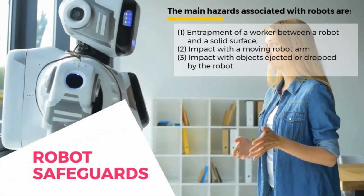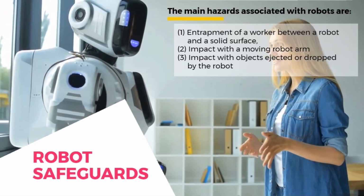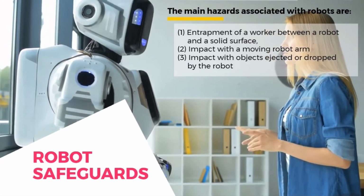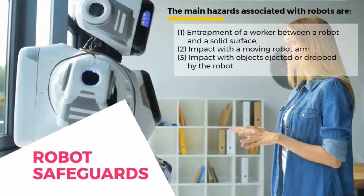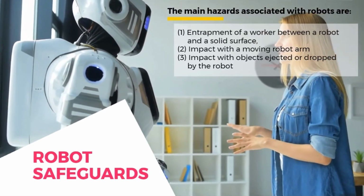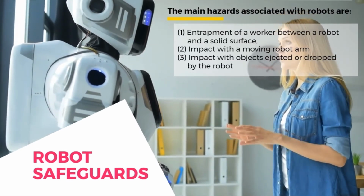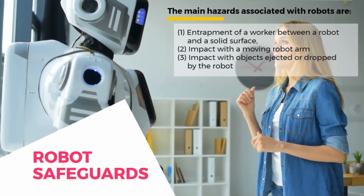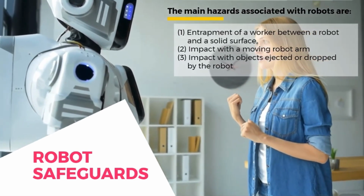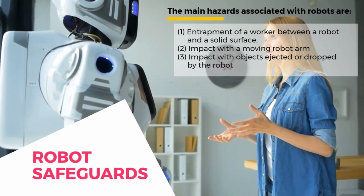Next, robot safeguards. The main hazards associated with robots are: 1. Entrapment of a worker between a robot and a solid surface. 2. Impact with a moving robot arm. 3. Impact with an object ejected or dropped by the robot. The best guard against these hazards is to erect a physical barrier around the entire perimeter of a robot's work envelope. This physical barrier should be able to withstand the force of the heaviest object that a robot could eject.